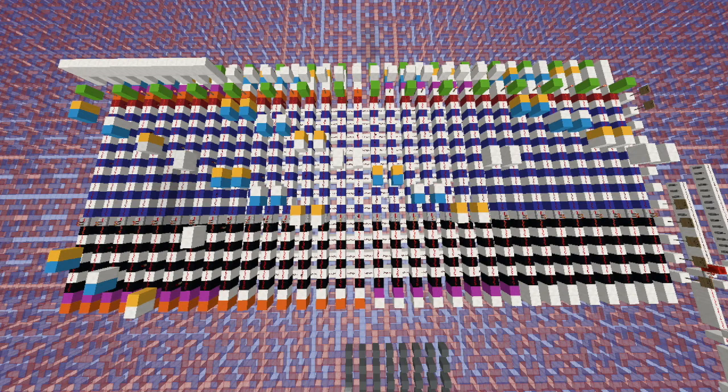We're just going to be looking at this grid that I have here. It's a bit hard to see what's going on, but it's just a standard ROM setup. The decoded shift inputs are the input wires to this decoder, and the desired barrel shifter inputs are the output wires. What we're going to need to do is create a circuit that doesn't decode every single wire, but still gives the same results as this decoder would.